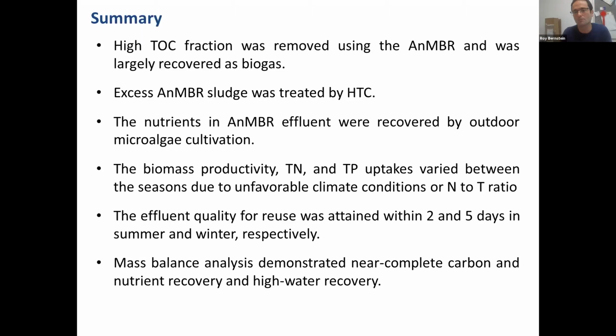Effluent quality could be attained within 2 to 5 days, depending on the season. This can obviously be optimized by just changing the biomass concentration in the bioreactor. And mass balance analysis demonstrated a near complete carbon, nutrient, and biogas recovery.